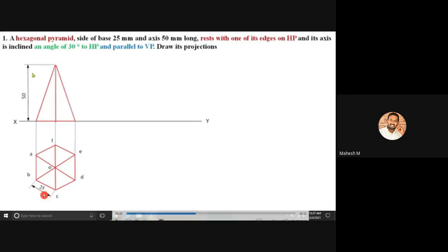If you're creating an edge hexagon, your axis line will not be visible because one slant edge will be in the same position as the axis line. So this is our front view, and you can see 3 slant edges.